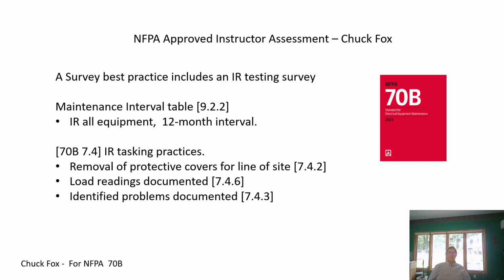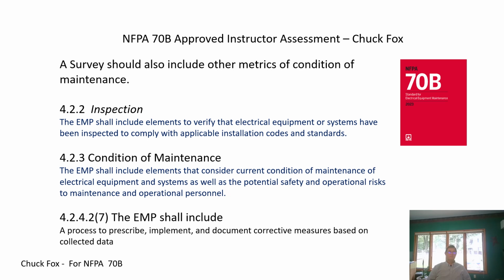One other very positive approach would be to have baseline IR images, so that each and every component has its own IR test, whether it has been tested as clean and good or whether there are problems as well. We also can expand this survey to include what I'll call other metrics of condition of maintenance. And again, 70B gives us some structure and direction on that.